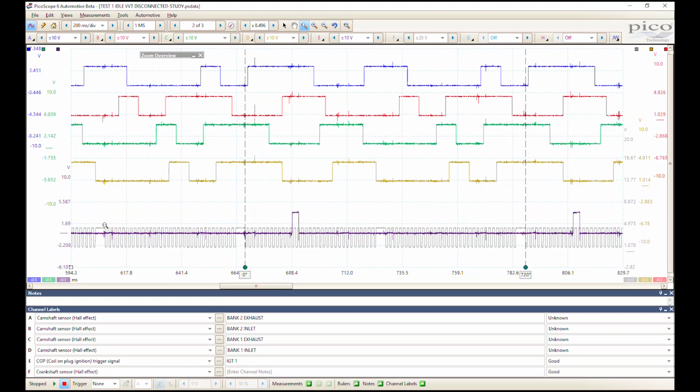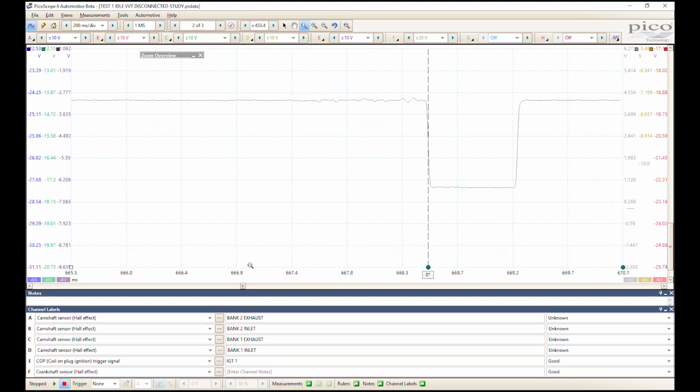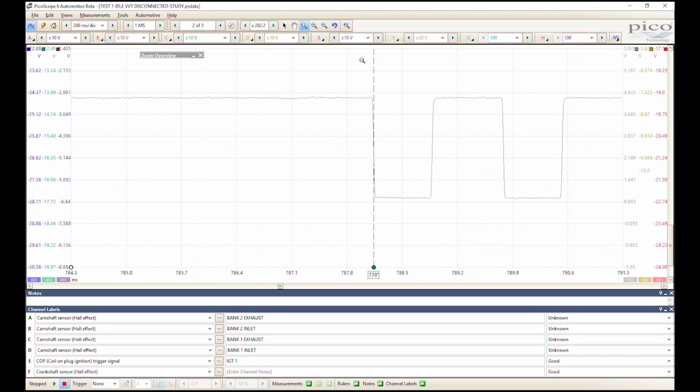So using IGT as our reference there, we count those teeth. We know that from this will be our measurement point, our reference point on the crankshaft, and not this one here, because here we have our tooth count, and from this point to IGT a far greater tooth count. So let's bring out the time rulers then. Let's make sure nothing's changed here. That looks good. That looks good.